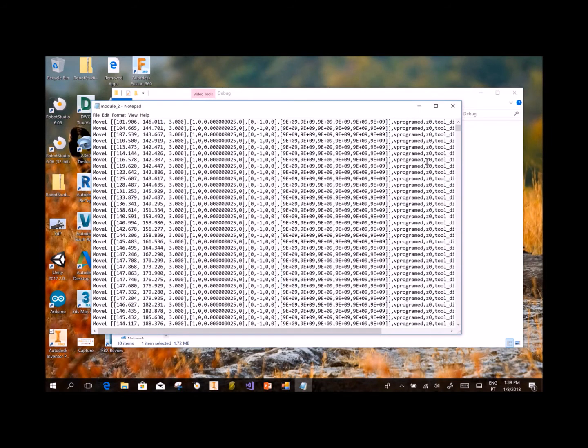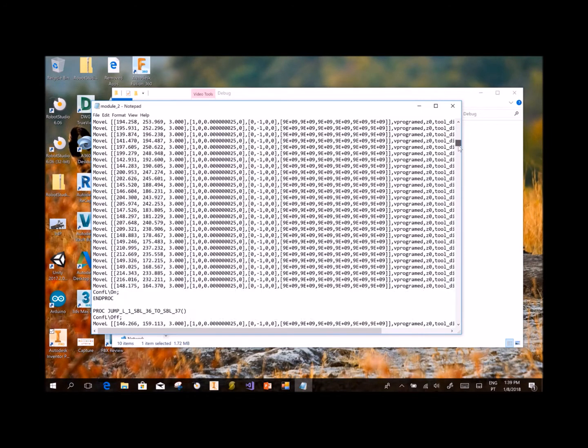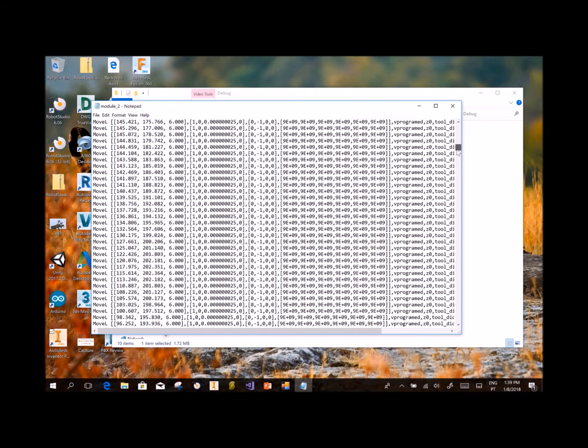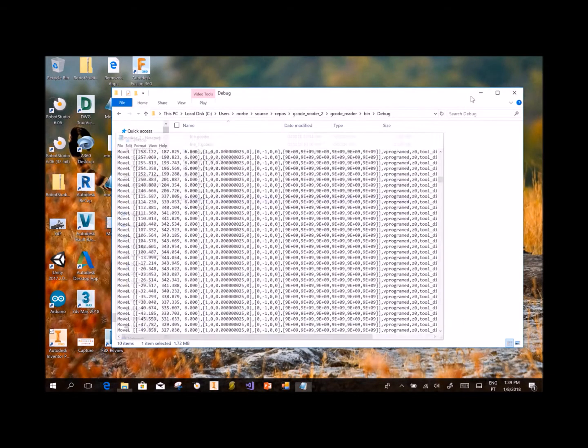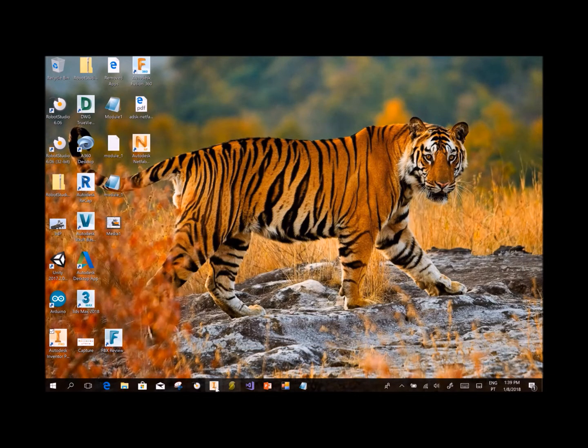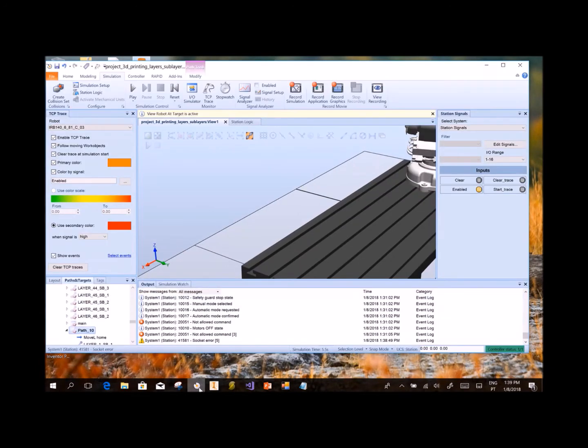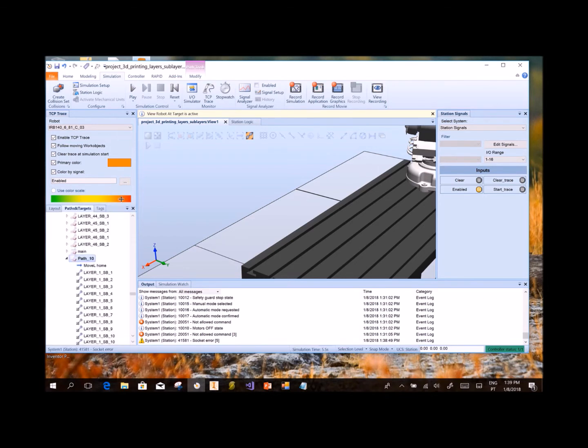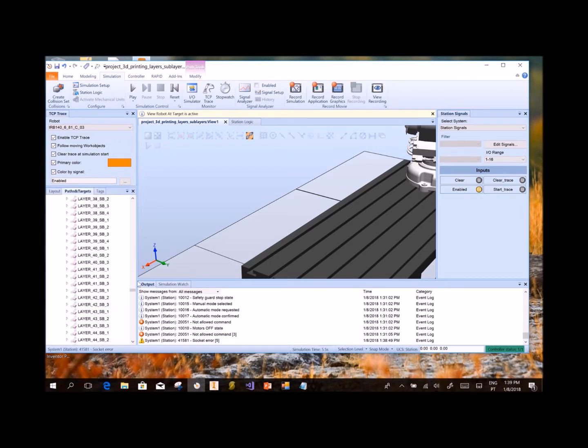as modules divided in layers, so moves of the robot to the generated X, Y, and Z positions, and then the only thing we need to do is to find the configurations necessary to do these motions. So I imported this to Robot Studio, and we have here all the layers available.